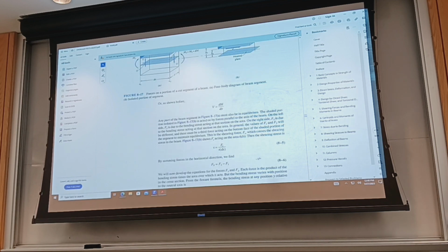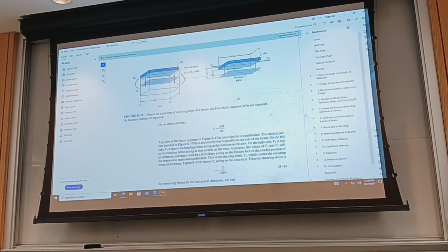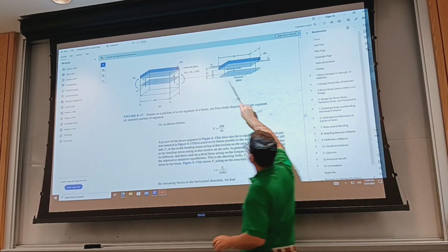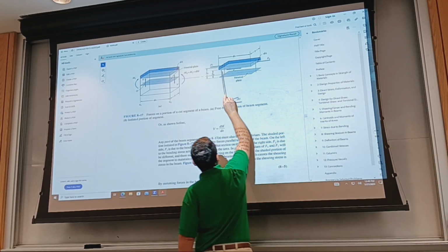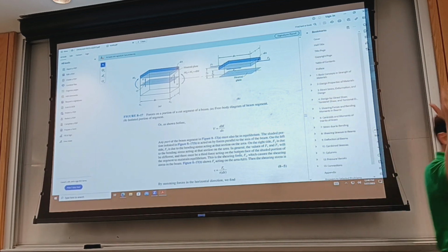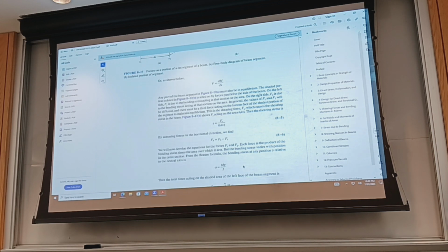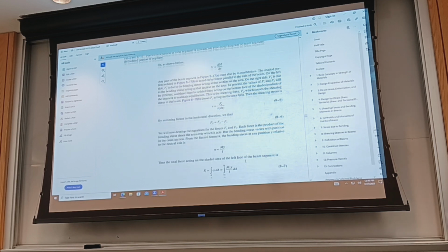Okay, so using the flexure formula to define the normal stress here and here, and then if you take that and multiply with the respective area, actually it should be an integral because that is not constant. And the shear force is the difference between the net force to the left and the right due to the bending stresses, which are unbalanced, like I said.